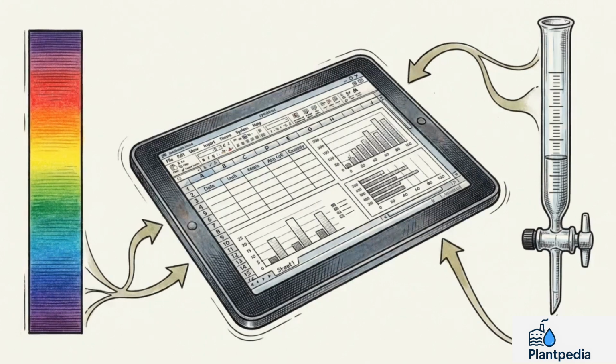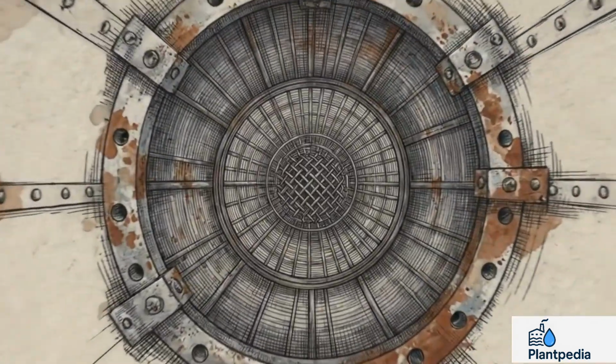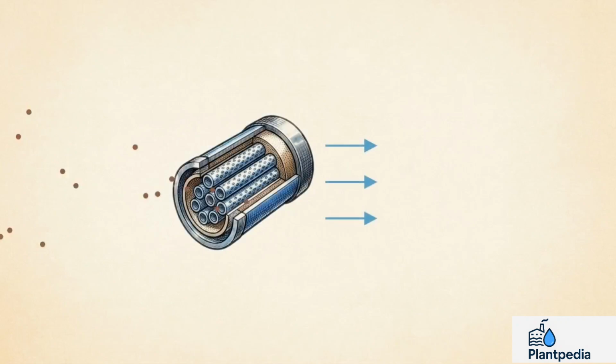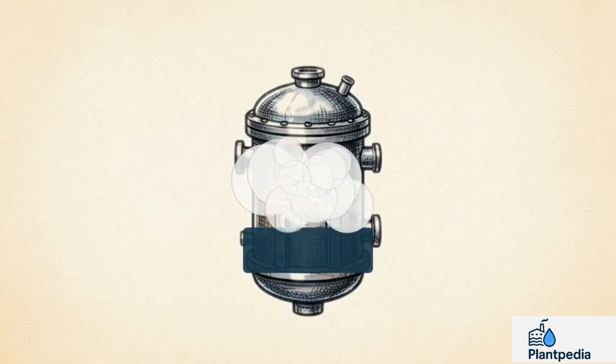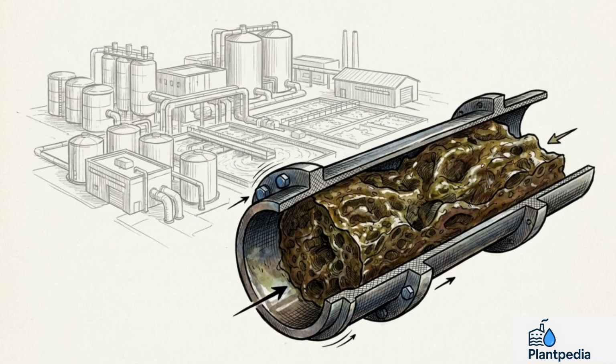So, what physically happens to your plant infrastructure when that data reveals COD limits exceeding 20 milligrams per liter? Here, organic biofouling creates a thick slime layer sealing the RO membrane's pores. Differential pressure spikes from 1.2 to 1.6 bar, killing permeate flow. Downstream in the ZLD evaporator, boiling triggers severe foaming, ruining heat transfer and destroying system vacuum. A high COD number is the direct, verifiable cause of mechanical strangulation across the entire treatment facility.